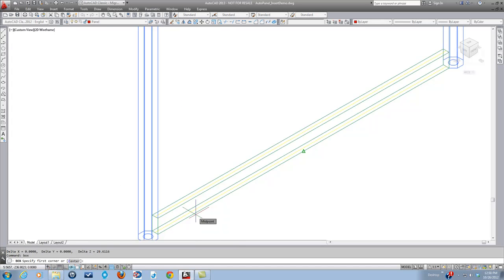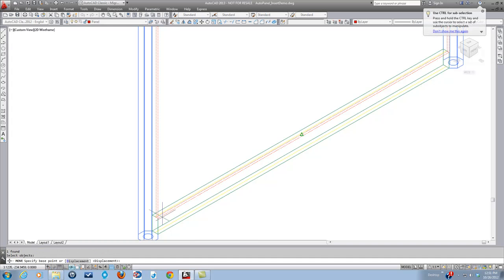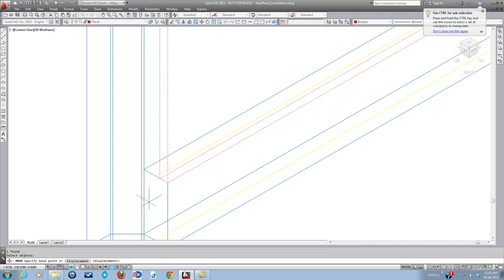We'll use the AutoCAD box command to create each three-dimensional panel object since it offers the fastest way to create them. Each panel is 1/4 inch thick, and all measurements are relative to the lower left-hand corner of the box. We'll use the Move command to center each panel object along the inside face of each crosspiece pair.